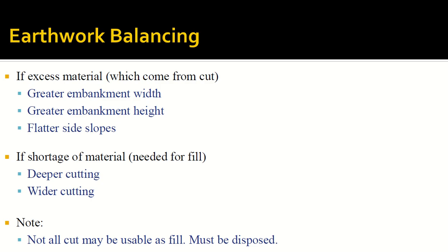If the soil is not usable, it is weak, it has high water content, it is very fine, then you will dispose it. You have to dispose it. Clear? You will not put it in the side slope or anything. It will make it weaker. So before you start filling with any type of material, whether from the side or you buy it, you have to check its strength and its suitability for the project. If it is not suitable, you have to dispose it.